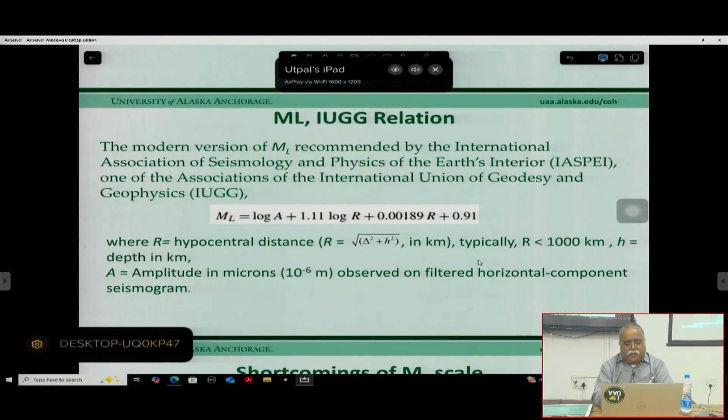But the Richter magnitude requires the Wood Anderson seismometer. Without the Wood Anderson seismometer, which is not present nowadays anywhere, except in one of the museums in California, they still have the Wood Anderson seismometer, and some observatories still keep one. But besides that, there is no Wood Anderson seismometer in place for active recording, right? Therefore, the ML scale does not make any sense.